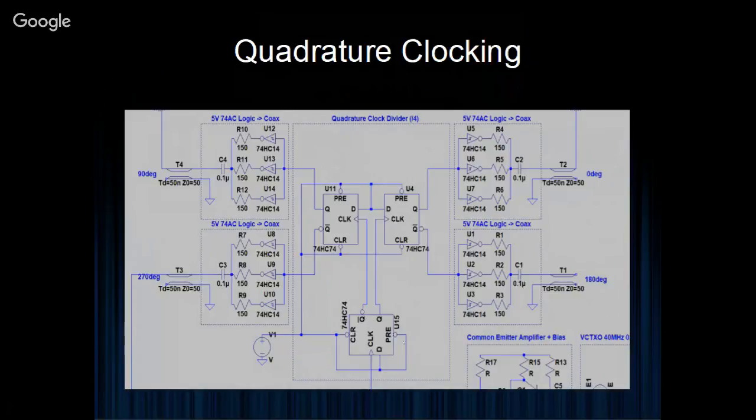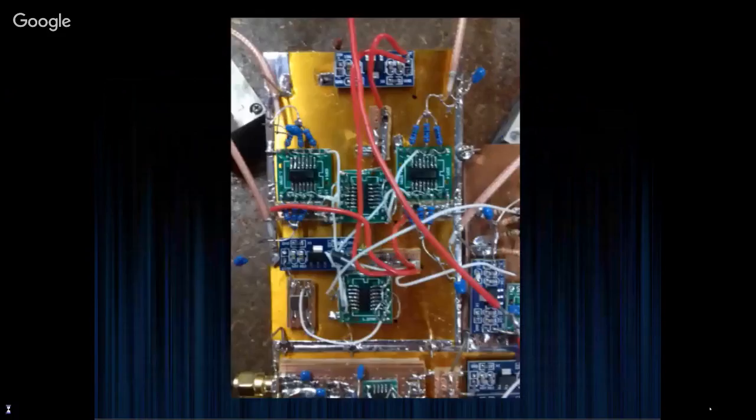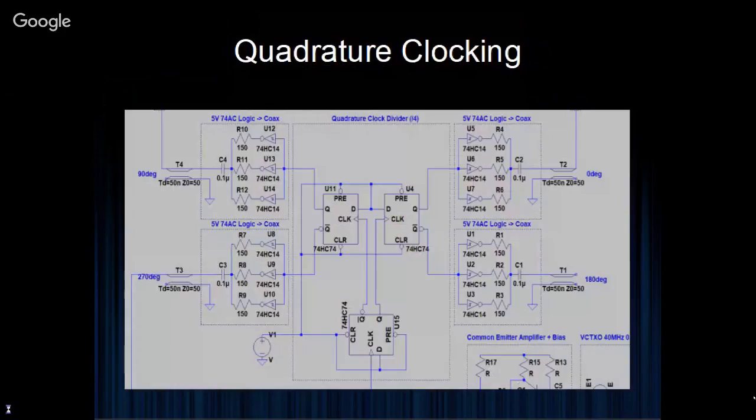But we'll move on to the next image, and you'll see where these signals get routed around the schematic, and also a practical and close-up look at how it's implemented in integrated circuit packages. How was it divided by 4? Because each edge-triggered D flip-flop in a toggle arrangement is divided by 2. I've cascaded 2 layers.